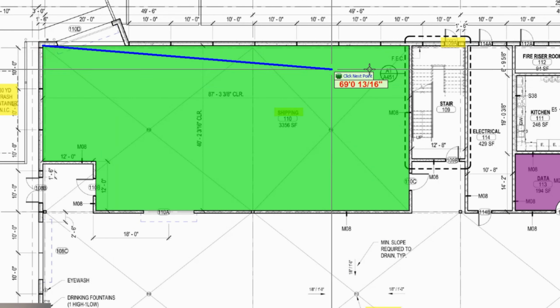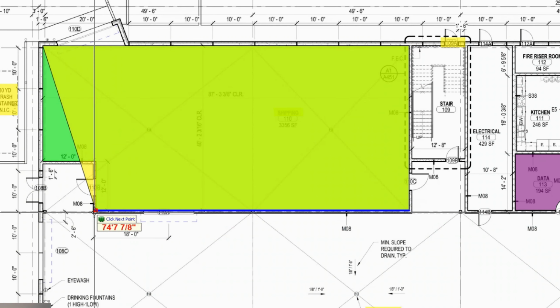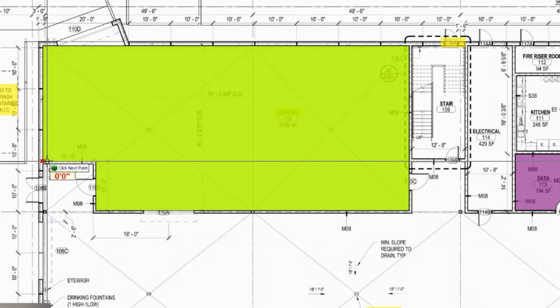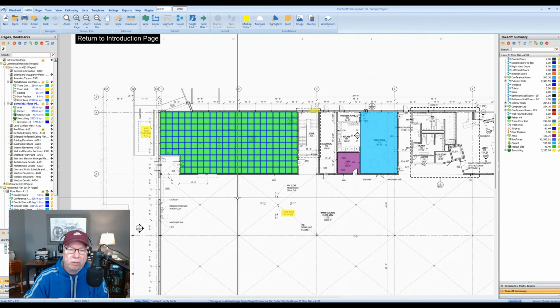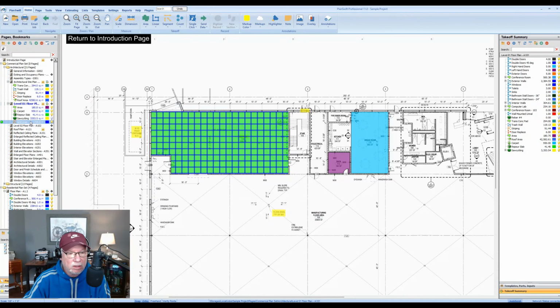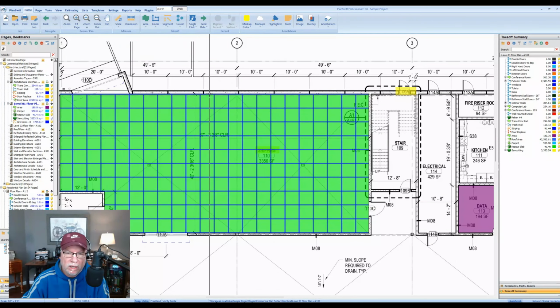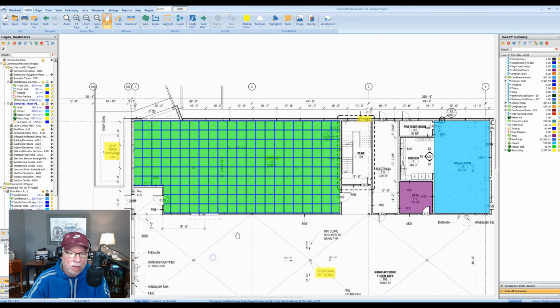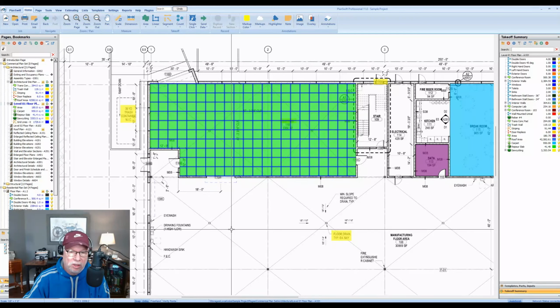And I just reuse that takeoff. That's why you have that snap tool in. And I should have told it not to use a color, because now I got the color in there twice. But there's my cut pattern. So I've got 1,700, call it 1,730 feet of cutting to get that slab out. Now, there's a lot of ways I can modify this for single cuts or double cuts and all that. And if you're not a saw cutter, you won't care. But think of this also as a way of designing your rebar pattern.